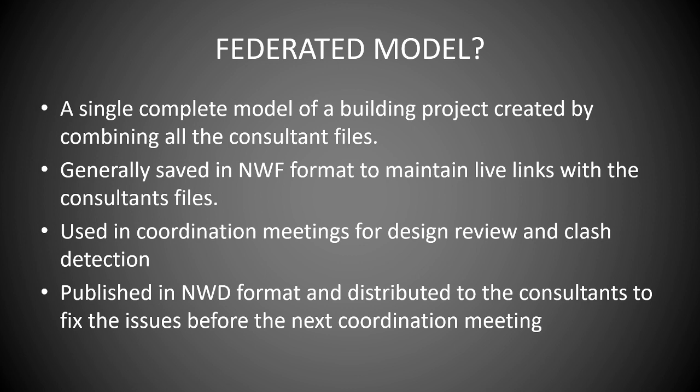Now, the NWF format is the format which has a live link with our consultant files. It means that if we update our consultant file, such as the RVT file which the consultant gave us, then accordingly our Navisworks file will be updated. So it has live links with the consultant files. So it is used in coordination meetings for design review and clash detection. I will explain these two terms: what are design review and clash detection? Then we publish this in NWD format after the coordination meeting and distribute it to the consultant.